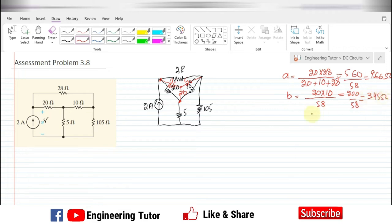3.45 ohm. Similarly for C, the denominator is again the same, which is 58, and the product of 28 and 10 will be written because at this junction 28 and 10 are connected. So 28 multiplied by 10 is 280 by 58, and ultimately the answer will be 4.83 ohm.